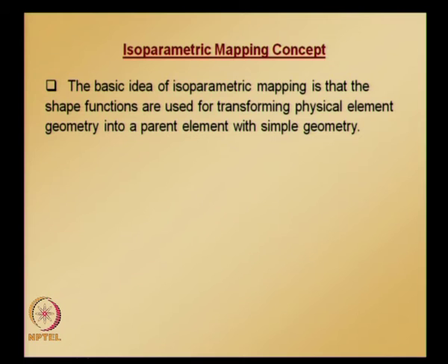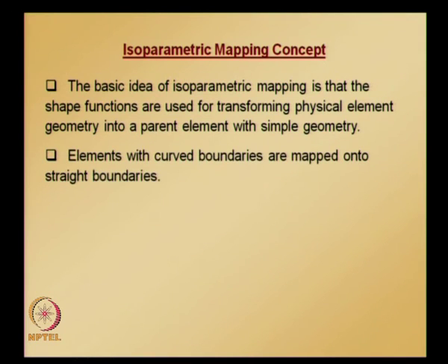So, the physical element, the actual element, we are going to map onto a parent element, and especially elements with curved boundaries are mapped onto straight boundaries.